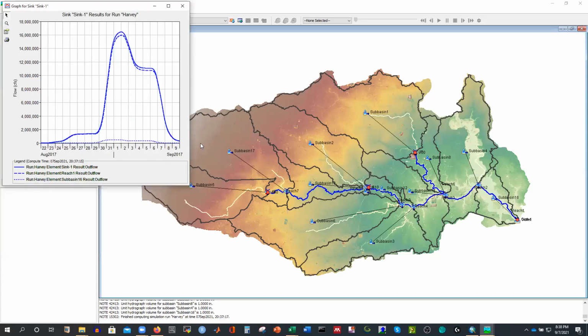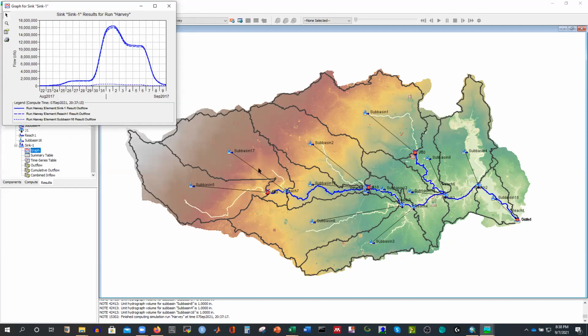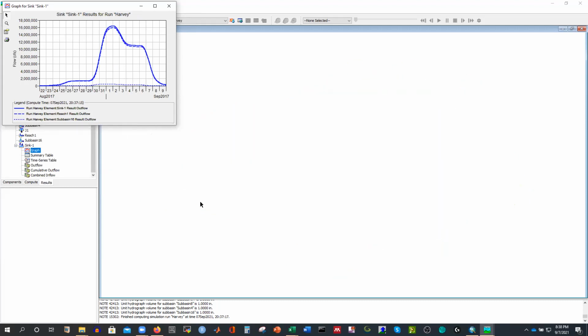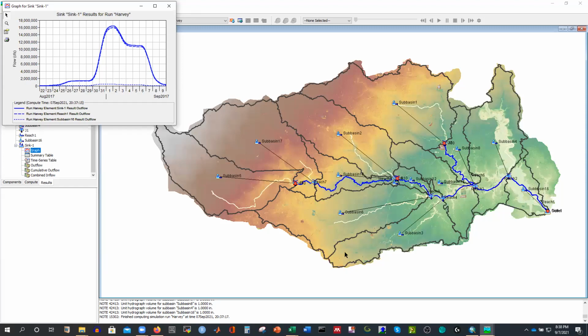So that's why you have to understand how to calculate the runoff pretty quickly using our DEM data. I was really amazed with the latest version of HEC-HMS, and that's why I thought, why don't I create a tutorial on it. Now I'm done with that one, and I'll even show you how to calculate the parameters, the basin average precipitation, and other model parameters. Then I'll run it again. That will be the second part, or even the third part, since this video is already maybe more than 1 hour, I don't know, but I think this is okay for now.